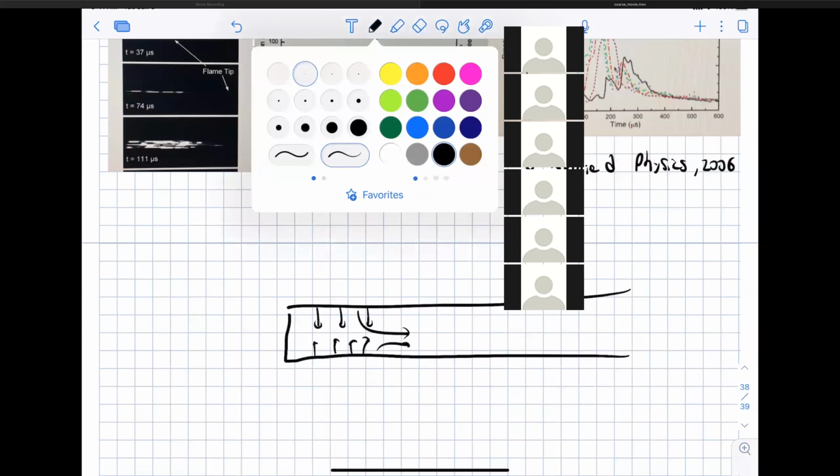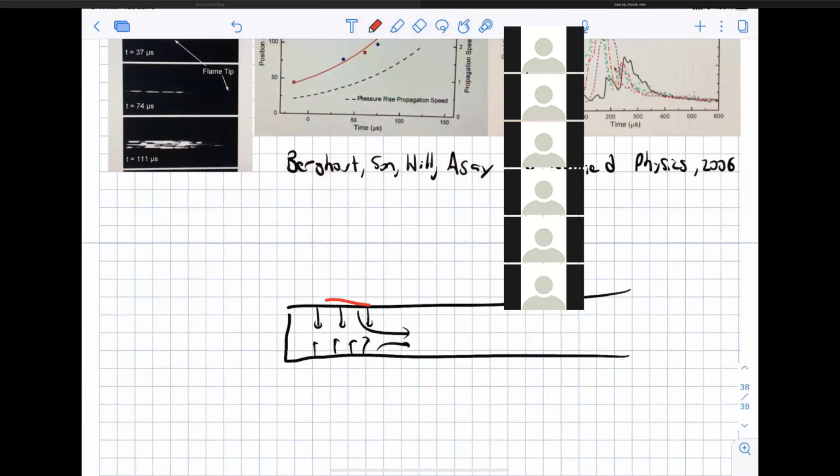So even if this is the section of propellant that is burning, you have high temperature combustion products flowing over the surface of the propellant here, heating it up. So there is a convective heat transfer effect going on. And as time goes on, there's enough burning area that you form a shock wave that can propagate, and that can also introduce convective heat transfer effects.